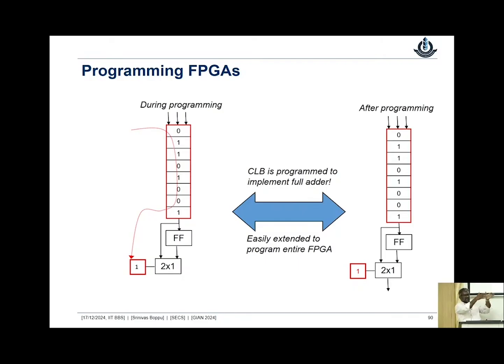They are connected in a fashion, and that is the reason many of the people, when configuring your Vivado project, don't select the right FPGA. So the bit file is generated but the tool doesn't understand it. That is the reason it's very important that when you are working with an FPGA, you select which FPGA you wanted to choose. Now the tool knows how big your FPGA is and what the CLBs are and everything, and then it will generate the bit file correctly.